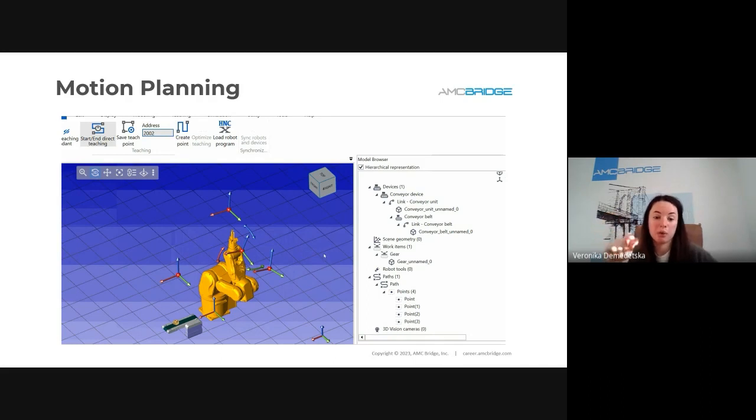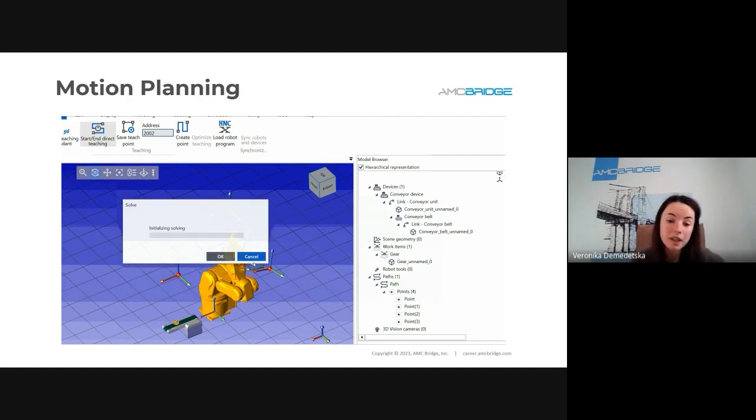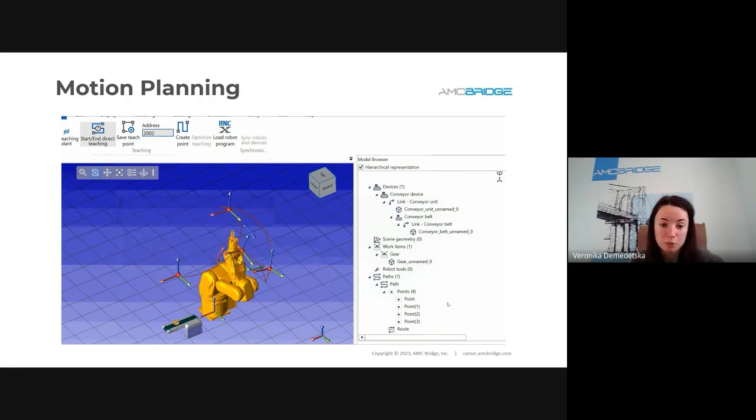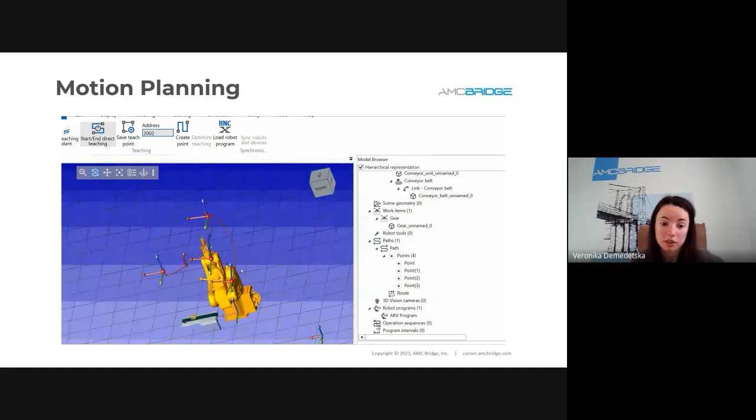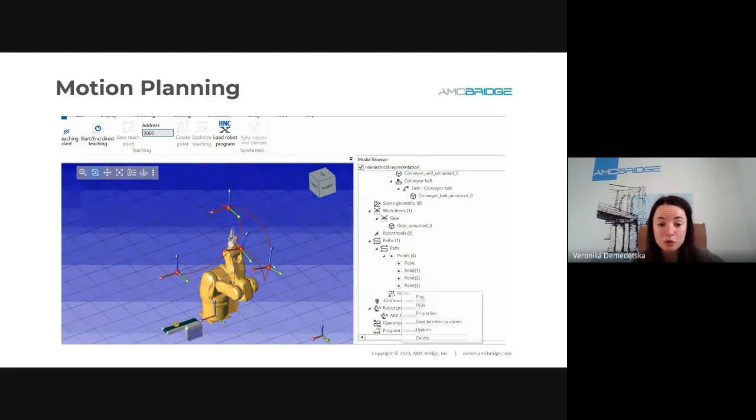We are setting the points for the end effector, for the TCP, where it should come. Then we can initialize the Robotics Library and pass all the geometry constraints, our joint types, and all other information that we need, and obtain the result. So the trajectory, the path for our robot. Yeah, in case we want to play that, it's going to look like this.